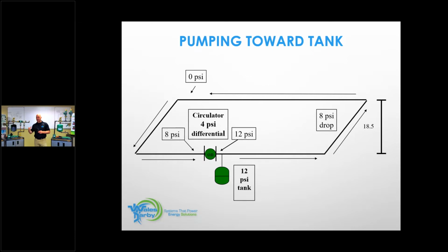And we see this a lot when we go out on jobs. They keep having an air problem on that third floor, second floor, whatever it is. So we'll go put an automatic air vent there. And every time we get to 0 PSI, we actually have the ability to suck air in through that automatic air vent. That needs pressure up against it, so it won't allow air to enter the system.